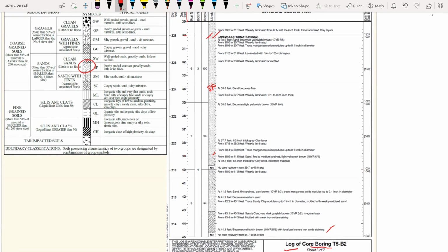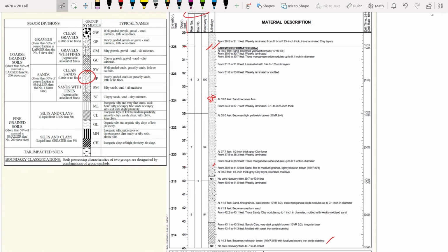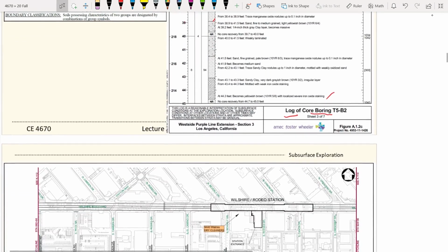So a soil boring log gives you the location where you bring the drill rigs to site to do your SPT or CPT. You core samples or you push the cone and then you get the information you need. Then you convert that back to soil classifications, or, as we will talk about a bit later, to the engineering parameters that we need, like density or soil strength parameters.